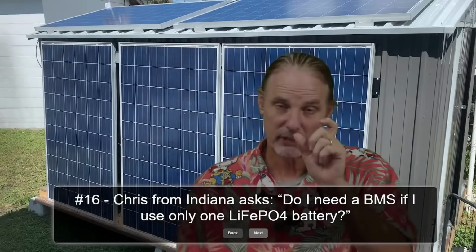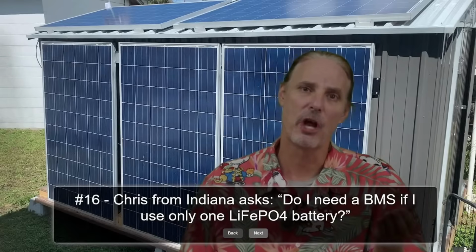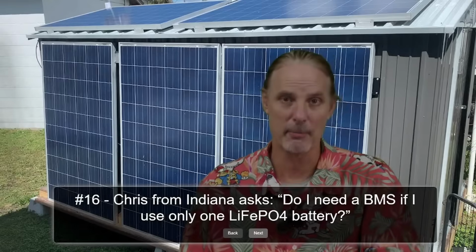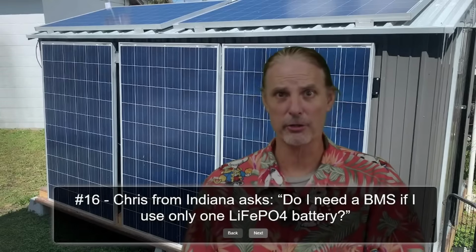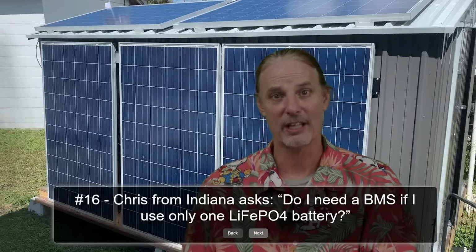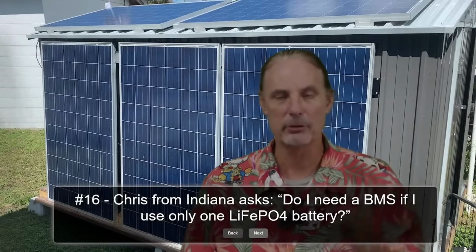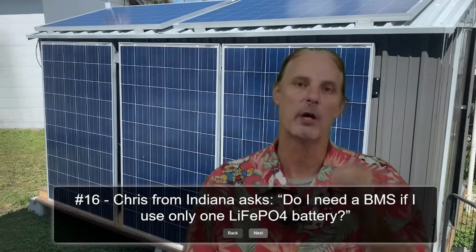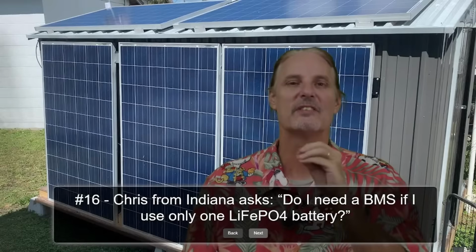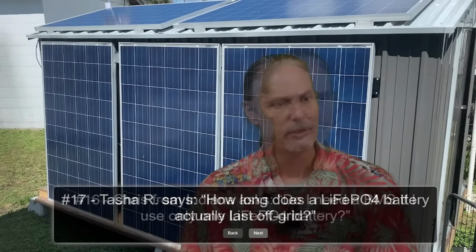Sorry about that. It monitors each of the cells and makes sure that you don't overcharge them or undercharge them too much and cause damage to the battery. It also monitors input and output of the battery for maximum pull, maximum push, to keep you from damaging it in that way. The BMS is, in my mind, an absolute 100% yes, you need one, and no, I wouldn't even consider thinking about using a battery without one.